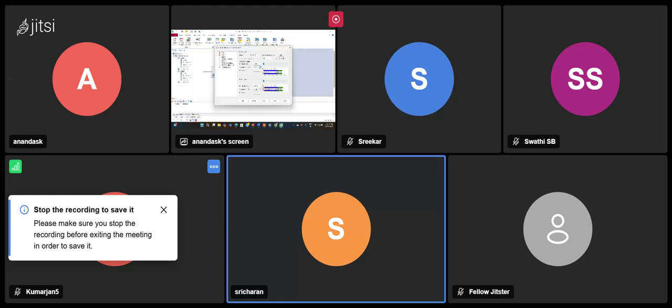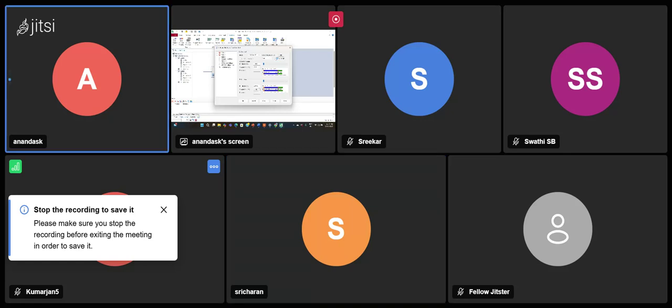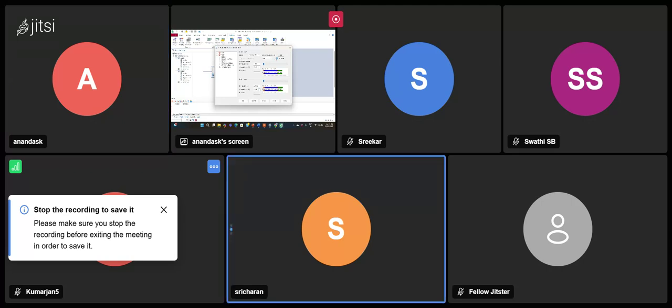And for the CAN FD transmissions, we also tick the TX self acknowledgement; that also will be enabled in CAN FD. It will give acknowledgement TX. Yes, because while doing UDS or anything, we want to get transmissions from the other nodes. In the CANoe configuration, we enable only one node and disable everything else. Sometimes, to get that data, we also have to enable that.